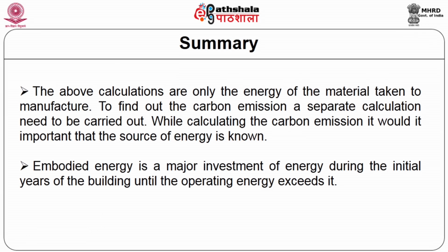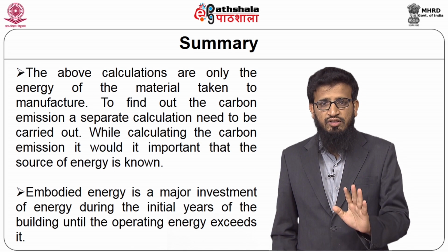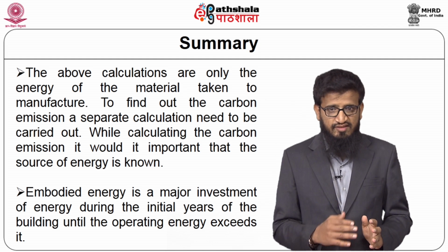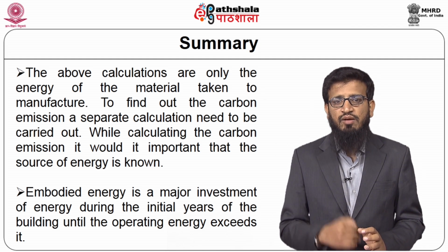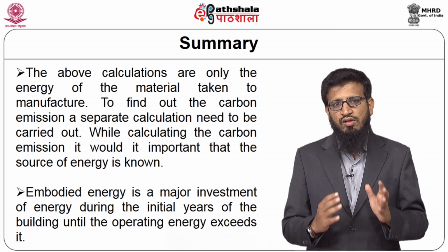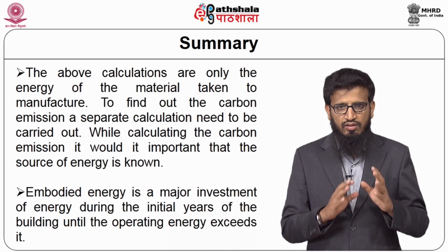As I mentioned, that is just the PER value. It doesn't take into account the transportation of the embodied energy, as this would vary significantly with destination and manufacturing. The above calculations are only for the energy of the material taken from the manufacturer. While calculating the carbon emission, it would be important that the source of energy is known. Here we are not doing the carbon emission. It could be the next step, if you want to go into more detail, to do the calculation for carbon emissions. But the module has been specified just to calculate the embodied energy.